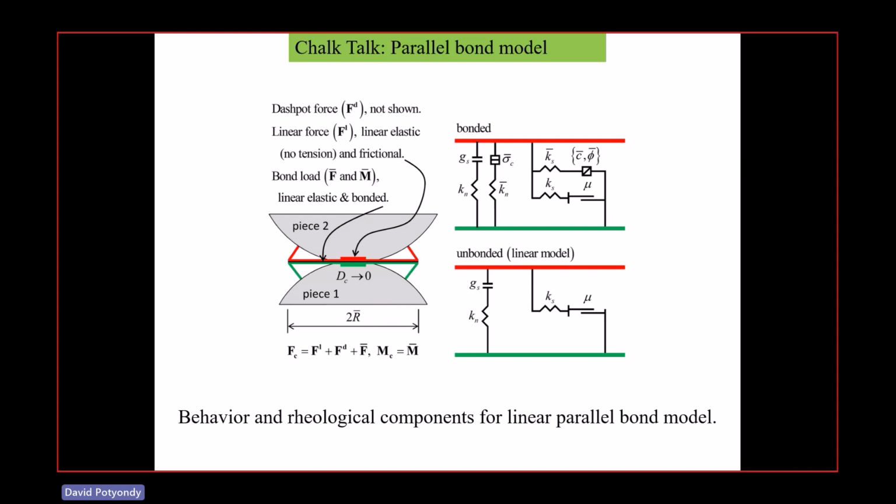In almost all rocks, there are all sorts of initial voids and gaps and slits. Those things only carry load in compression, not in tension. So when you pull a rock in tension, there's less material resisting than when you push it in compression. This is something that's naturally happening in this parallel bond.